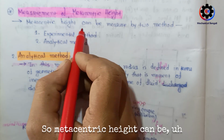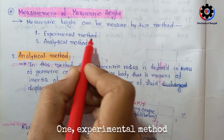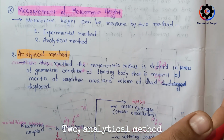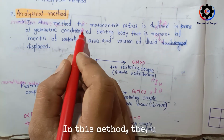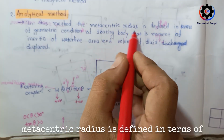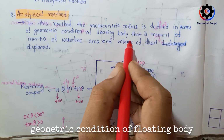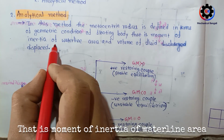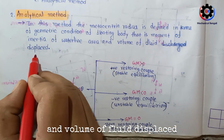Metacentric height can be measured by two methods. One, the experimental method. Two, the analytical method. First, focus on the analytical method. In this method, the metacentric radius is defined in terms of the geometric condition of the floating body, that is, the moment of inertia of the waterline area and the volume of fluid displaced.